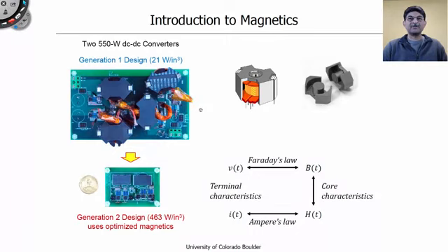Yes, there is. Unlike other components that you will buy off the shelf and simply need to understand how to read their datasheets, in the case of magnetic devices, it is very rare that you will find something suitable for your specific power electronic application. In general, you will be designing and fabricating your own magnetic devices for your power electronic converter.